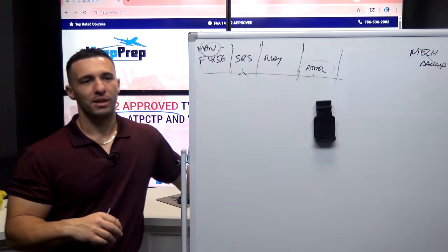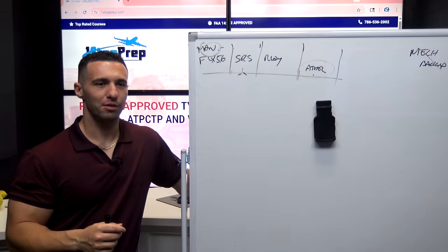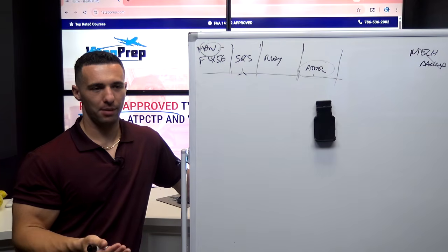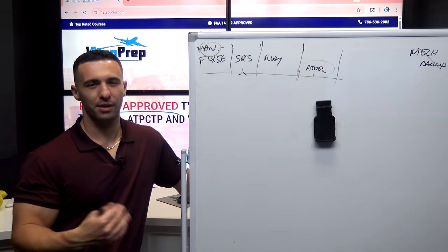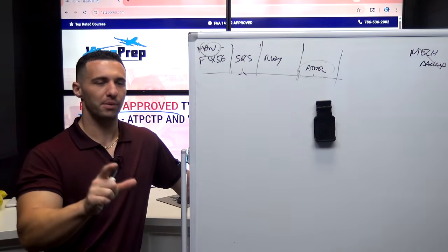So, kind of a long-winded answer. But yeah, you could fly below it and then monitor it. And then I would probably configure to the next flap setting if you're starting to get pretty far from the optimal.